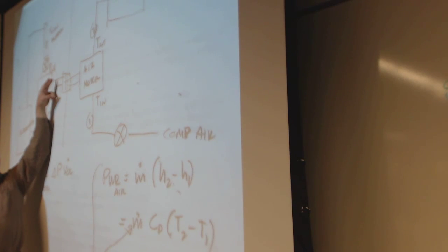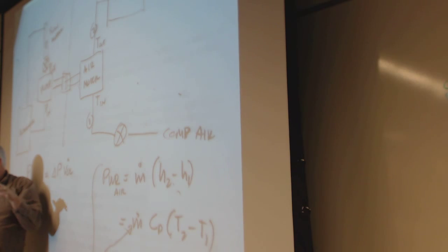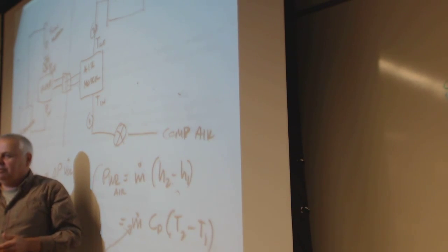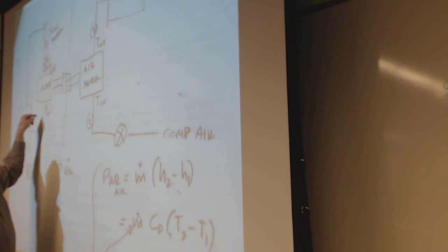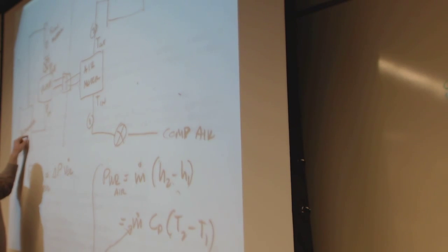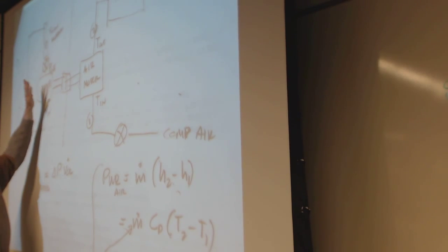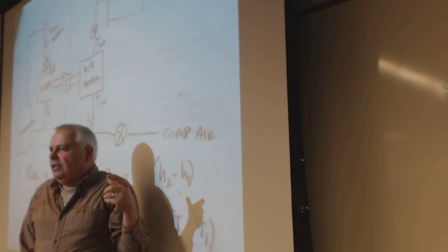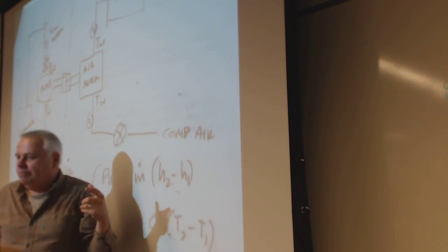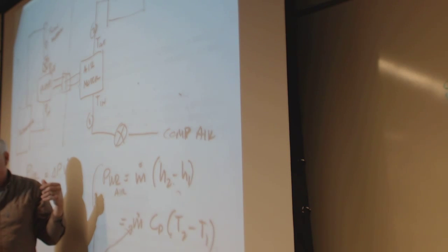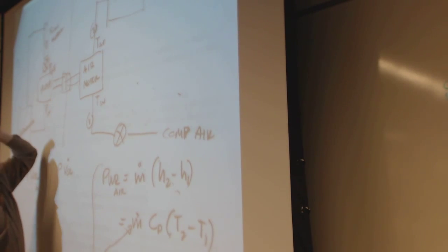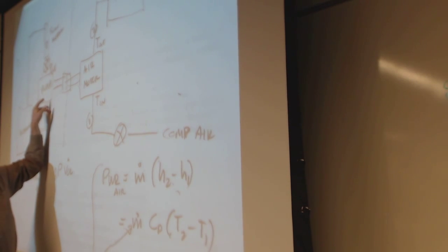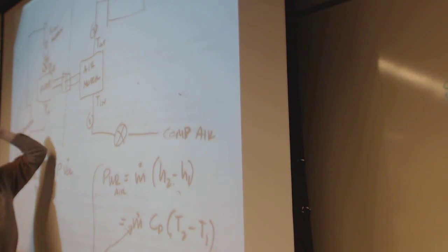The water density does vary with temperature, but the temperature is not changing much. The biggest problem with this is if this generates air bubbles and you end up with a bunch of air bubbles pumping through here, that will definitely affect your reading. So you will get some of that, but be aware that you want to avoid that because that'll change this reading. But we don't care about temperature over here. It's all about pressure in, pressure out, and what the volume flow rate is.